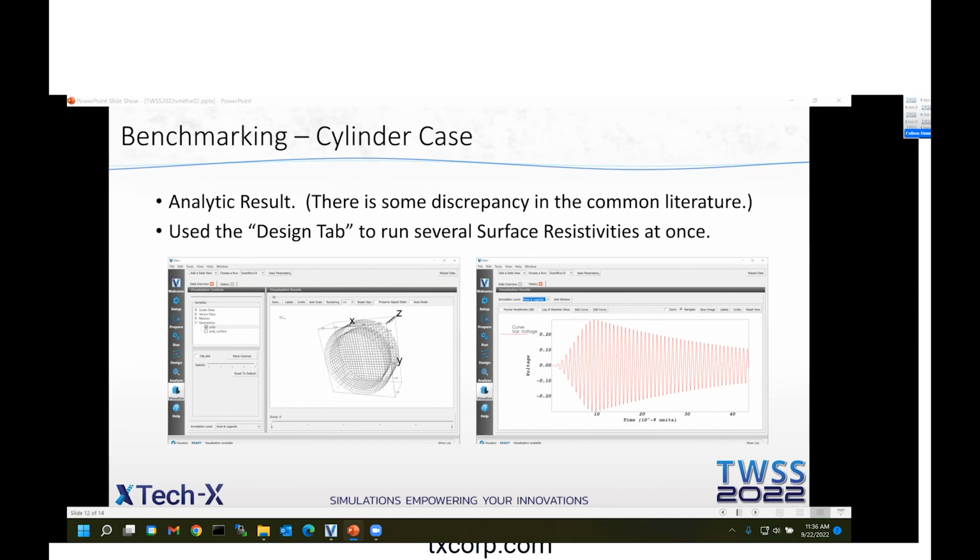And another question that came in through the chat. How do you get around from resolving the skin depth? Well, the skin depths in these typical devices, when you're running at gigahertz, the skin depths are microns. And the cell size might be a millimeter, or maybe even 1/10 of a millimeter, which is still 100 times larger than the skin depth. And so there's no way that you can resolve the skin depth with your finite difference mesh. So that's why you're using this global model of current and surface area. And we're not trying to do that.